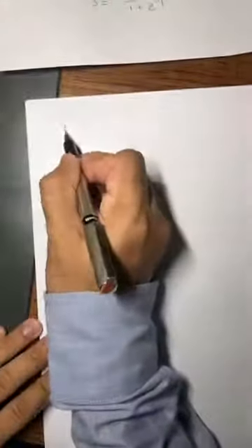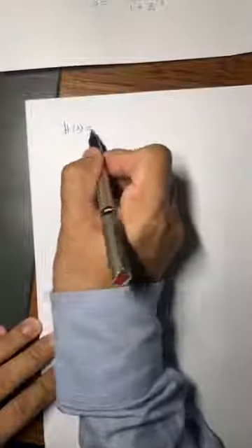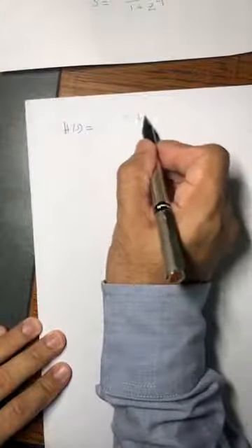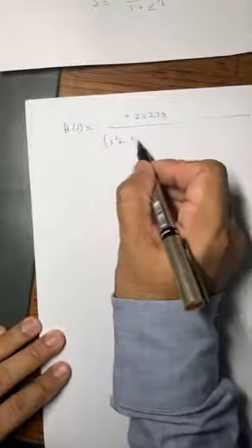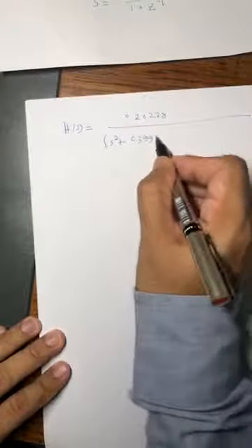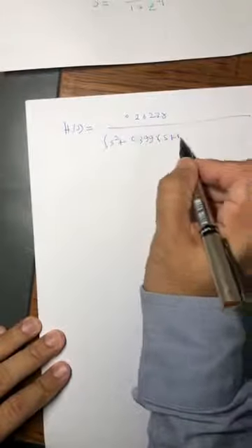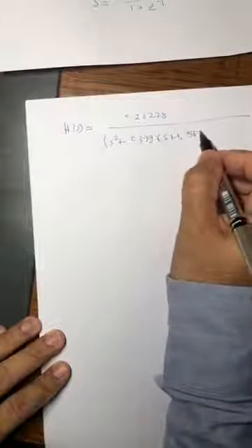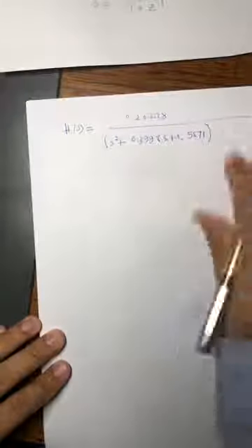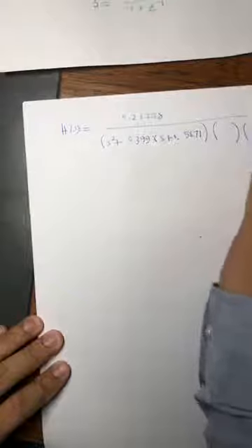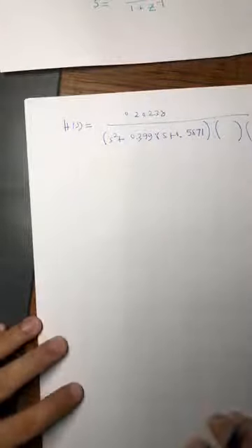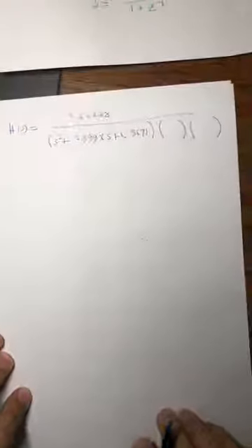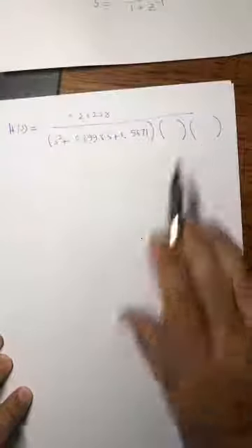So interestingly, you will find out that your H of s will be something like this, 0.20238, now writing exact expression, s square plus 0.3996s plus 0.5871. This is the first, and then there's going to be a second order, second order, okay? So once you combine the 3 complex conjugate pairs together, you get this as an expression.